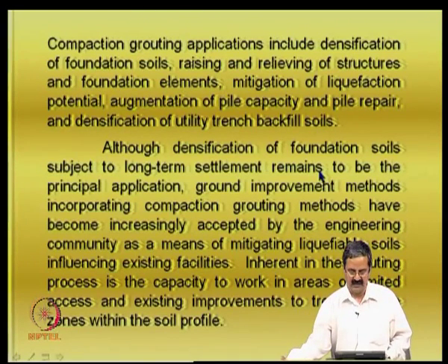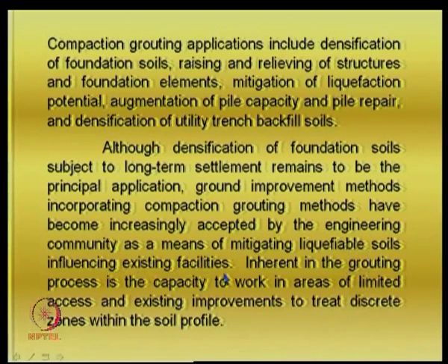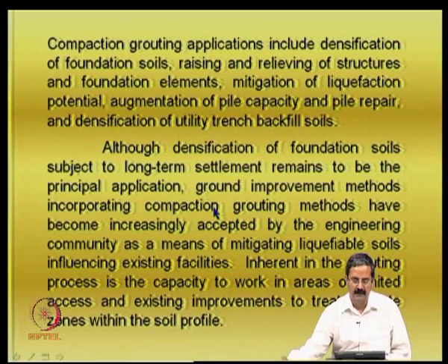Although densification of foundation soils subject to long settlement remains to be the principal application, ground improvement methods incorporating compaction grouting methods have become increasingly accepted by the engineering community as a means of mitigating liquefiable soils influencing existing facilities. As I just mentioned, since you have excellent equipment and quality control, like machine control, the possibility is that yes, this method can give good improvements.